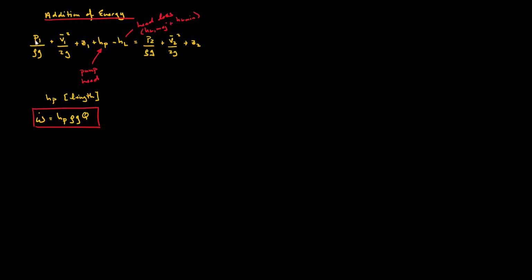We introduced the concept of head loss, noting that we have major losses due to friction occurring in straight pipe sections in a fully developed flow, and we have minor losses due to pipe fittings, expansions, contractions, etc. Then finally here we have the most general form of the mechanical energy equation, which has units of length, and here we see that we have terms for the addition of energy to the system, and we have our head loss term HL, which extracts energy from our system due to friction and minor losses.